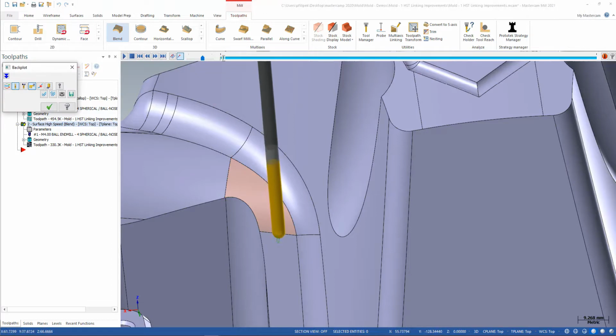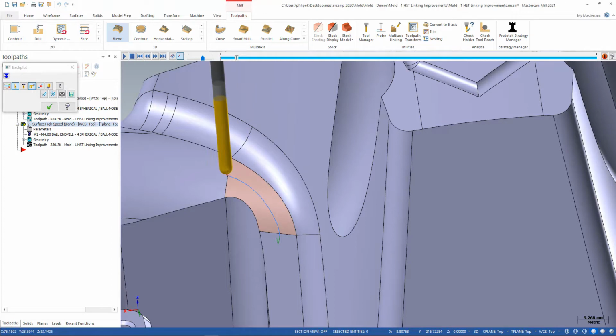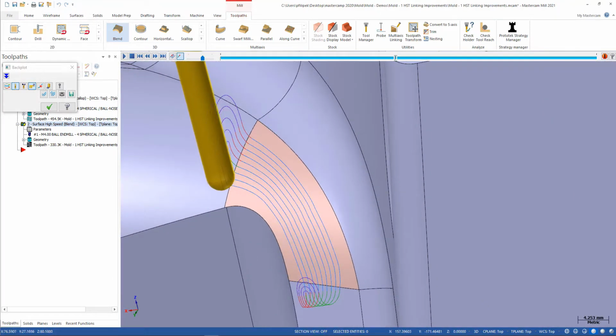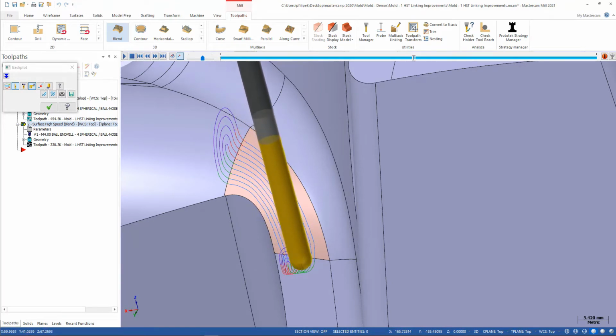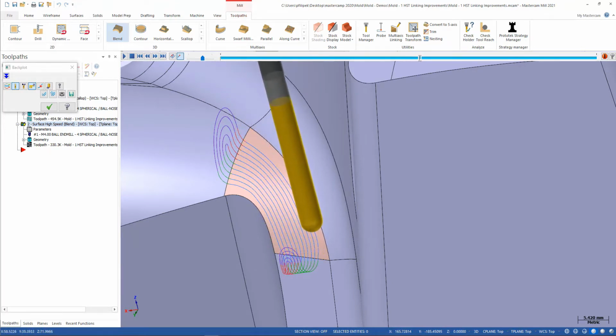So I'm starting at the center and working my way up out of the cut, rolling back down. It's a really nice transition this way. So it's easy on our machine to do that nice roll over that cut, roll back into the edge. And I'm on contact point, so it's making sure it's maintaining a cut all the way down to the bottom of that surface and rolling back in, rolling all the way back to the top.